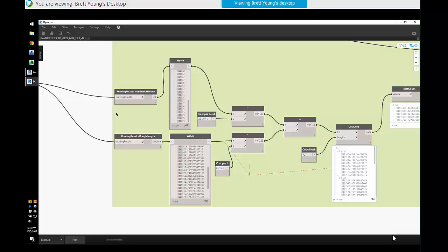So in that example, the good question is, if you had lowered that duct enough to get those 8 conduits over the top of it, that might have been a more optimum project solution for that example, or it may not have been. The traditional thinking would be that duct is expensive to move and wouldn't be able to go and do that. But if that had no cost to you, you could do it easily, then it would have a savings for the project. Right? And all those conduits would be dead flat over the top.